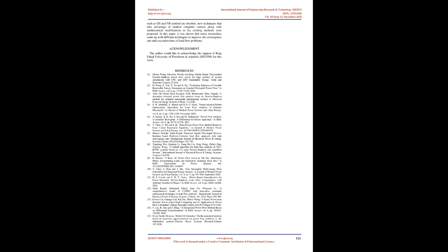Nonlinear iterative solver using graph computing [13]. For a large-scale power system, Gauss-Seidel method is not as frequently used as NRPF and FDPF to solve power flow problems, due to its low convergence rate and long computation time. The author of this paper [13] proposed a nonlinear iterative solver, NLIS, based on bulk synchronization parallel computing model, BSP, by restructuring GS using PageRank algorithm on a graph computing platform.